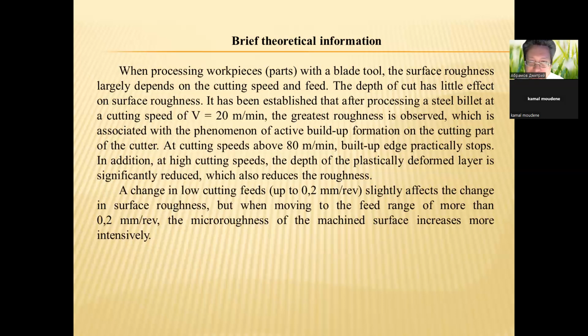It has been established that after processing a steel billet at a cutting speed of V equal 20 meters per minute, the greatest roughness is observed, which is associated with the phenomenon of active build-up formation on the cutting part of the cutter. At cutting speed above 80 meters per minute, build-up practically stops.